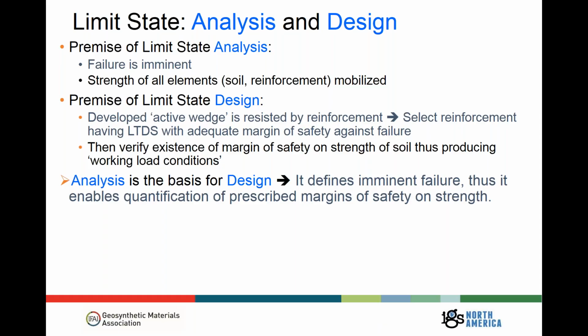The premise of limit state design, in its current form, is that we look at developing an active wedge or some active body that's resisted by the reinforcements. Based on that critical failure mass, we can select a reinforcement with a long-term design strength, that's what LTDS stands for, with an adequate margin of safety against failure. Then we can verify the existence of this margin of safety on the strength of the soil, producing working load conditions.